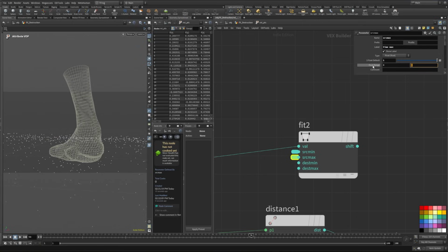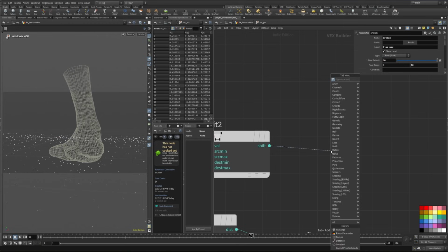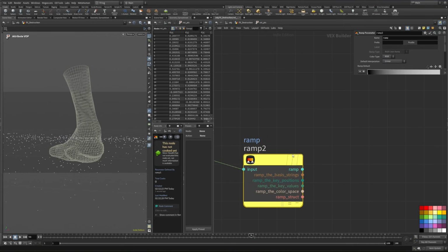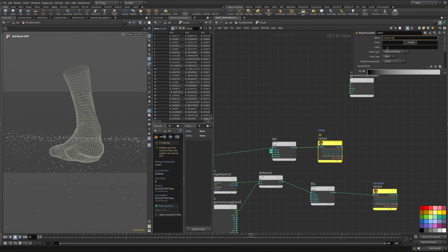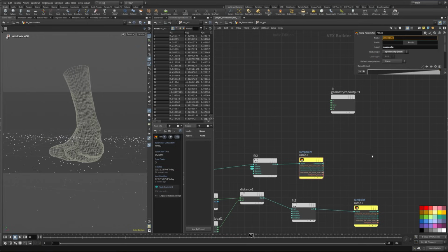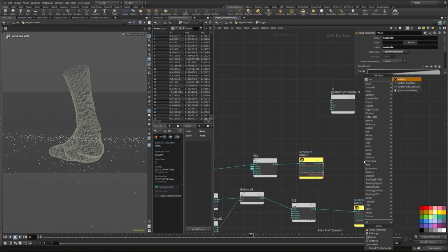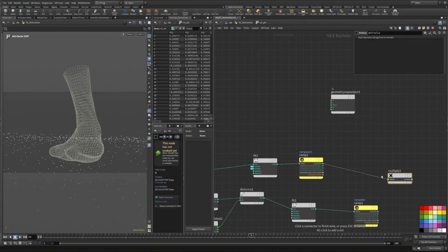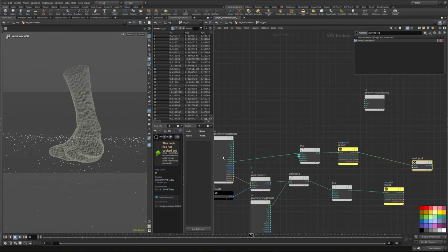And I think I'm using a value here of 50 and the float value default of 36, like so. Let's drag it into a ramp again, and this will be my ramp animation, like so. And this also has to be a spline ramp. Make sure you also change the name if you have more than one ramp in here. And let's use a multiplier over here.